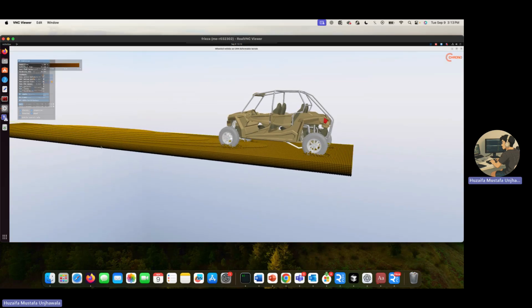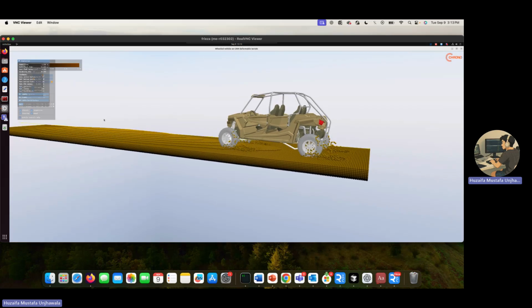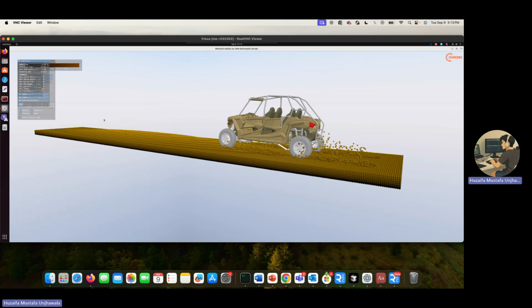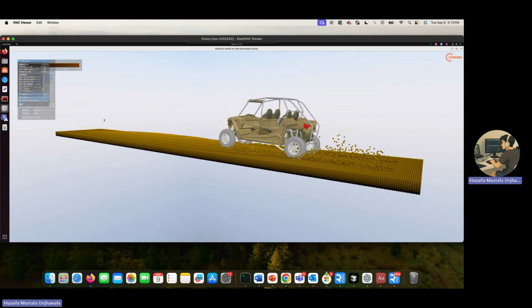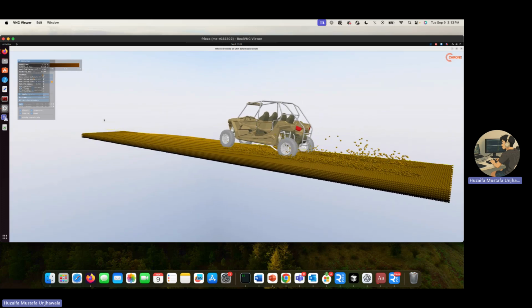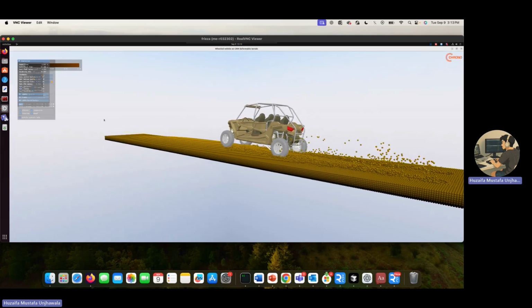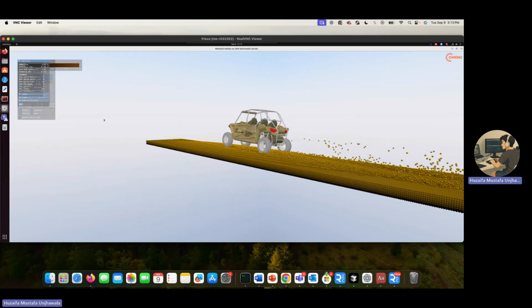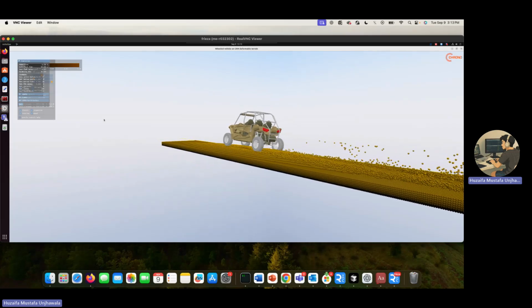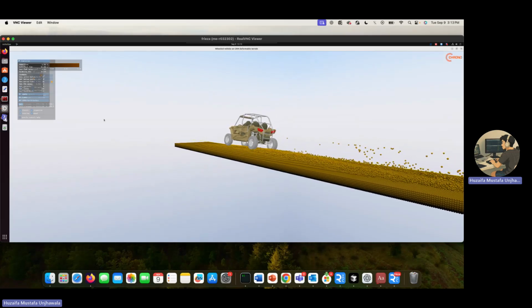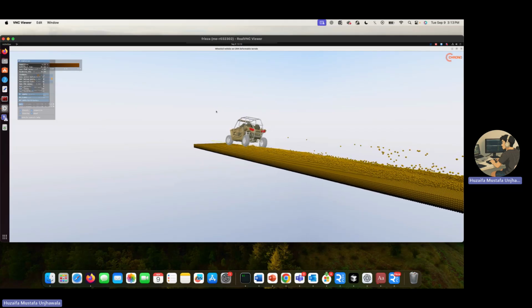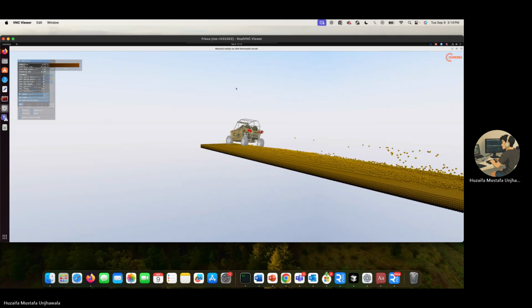So I don't know how I will show you this, but if you go all the way down and look from below, you'll see that the BC markers have moved up, and you have a uniform 0.25 meters depth along the entire terrain patch. So below this bump, it's not like there is 0.25 meters and then the bump. It's uniformly 0.25 meters, and so the bottom surface moves up. But I realized I can't show you that because I'm not able to rotate for some reason on this computer.